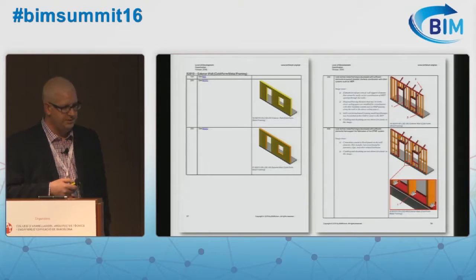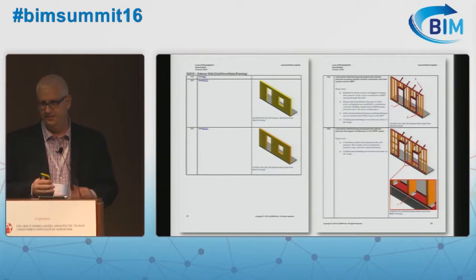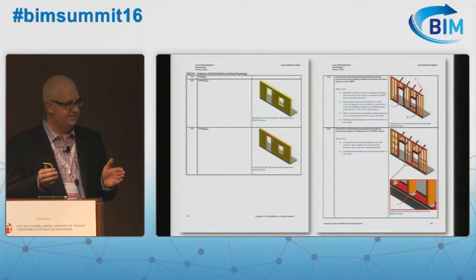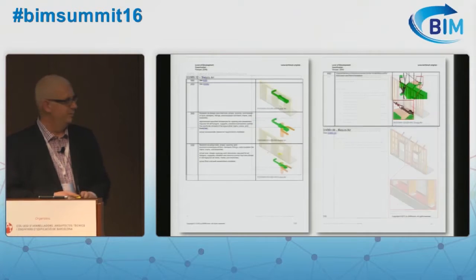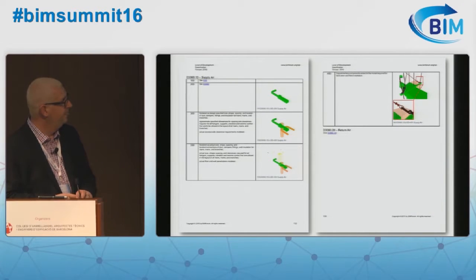We look at interior walls. We go from something that's just represented as interior versus exterior, it might be skinnier or wider, to actually an accurate and specific assembly with its layers and overall dimensions. And as we go to 350, we start to see all the major structural components and kickers and other things that start to work that system together.